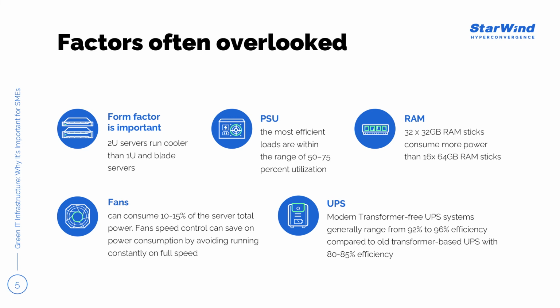However, the other important thing to note is that the UPS does not always operate as efficiently as its rating suggests. When you see the efficiency rating, this means the full load, basically 100%. The load factor can be different.